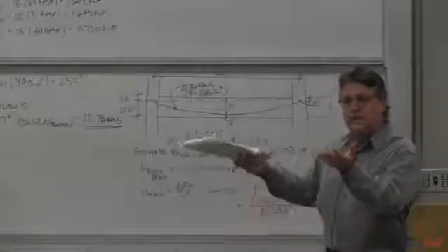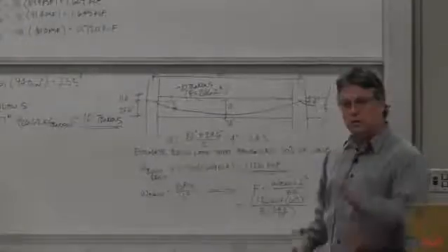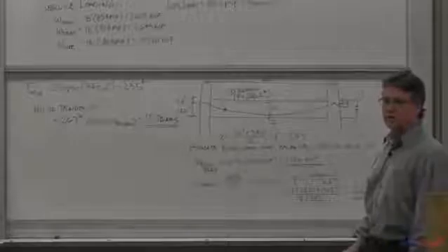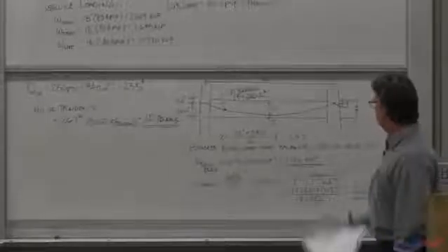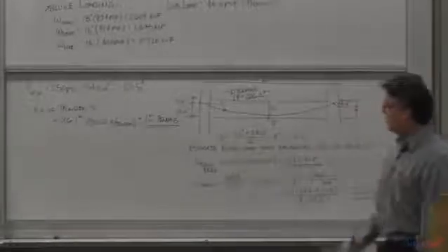It's the non-controlling span. So if you're shooting for balancing 70% of the concrete weight and you're balancing about 70% in the controlling span, you might want to balance a little bit less in the other span. Remember, that had a big effect on the stresses in the controlling span. So you don't want to overbalance. You want to slightly underbalance the non-controlling spans and balance as much as you can in the controlling span.